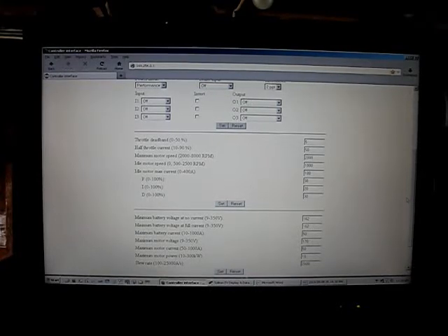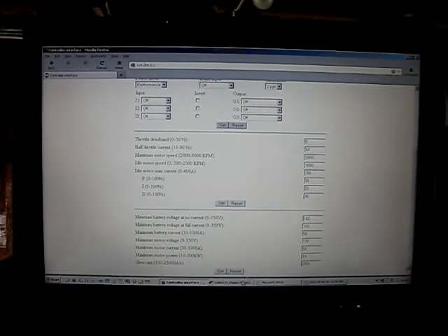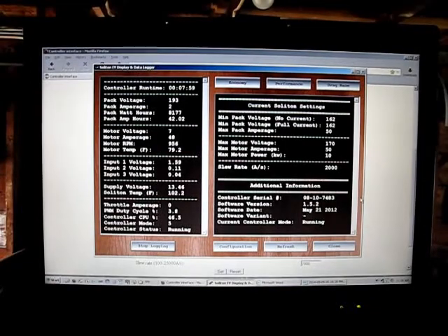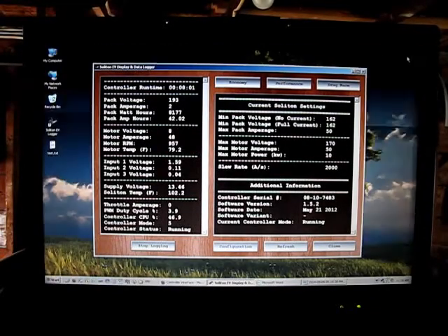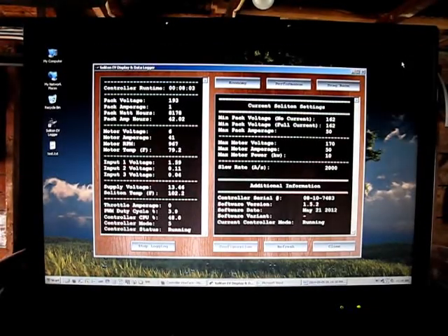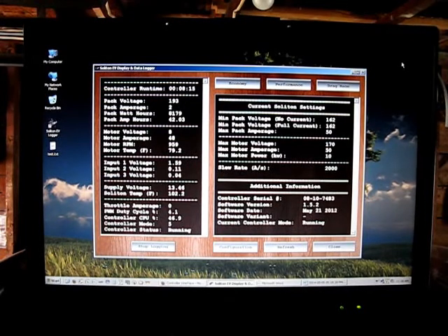So because the amps roughly equals heat, I think that it's probably a good idea to keep that amperage limited during the brush seating process, and let the voltage go up to the NetGain spec if we need to, in order to hold that RPMs. But anyway, just kind of an interesting thing. Not really sure if it means anything at all, but at this point we're back up and running, and the motor is